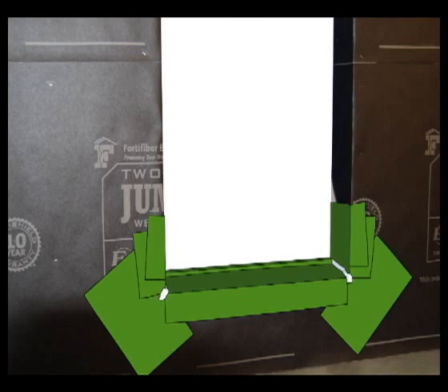A pan flashing creates a waterproof barrier between the structural compartments that make up the bottom of the window rough opening and the liquid moisture that may accumulate at this location. The window rough opening pan flashing should run up the sides of the window rough opening a minimum of 8 inches.